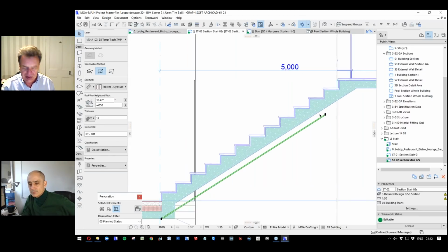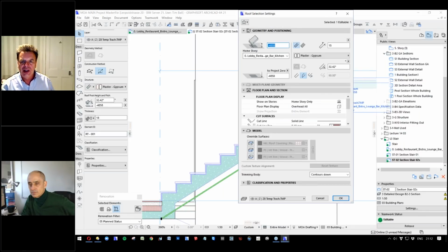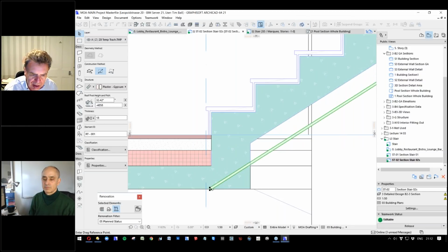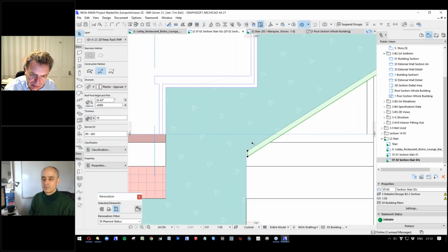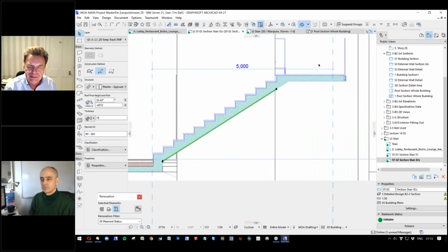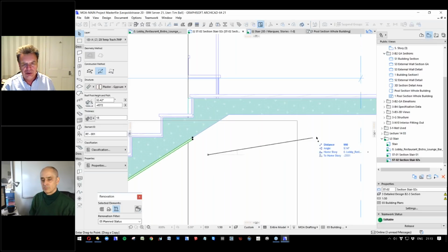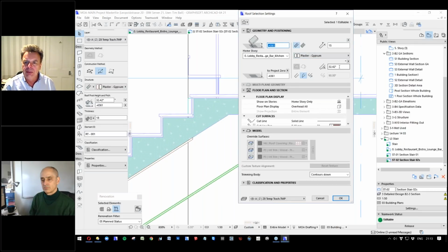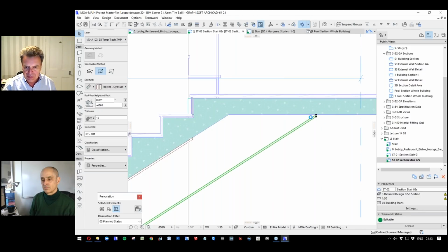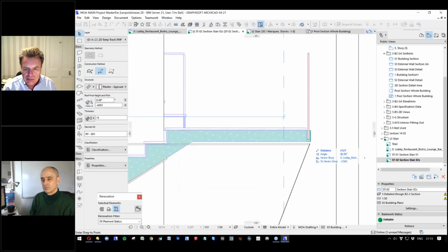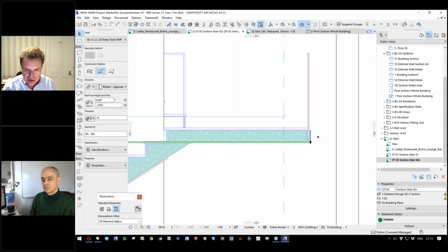So basically, this is actually a roof. You take a bit of roof, you make it plaster, you get the angle right, you get the thickness that you want. I put this temporarily on another layer so I could bring it in, and you take that to there. Getting that connection would be quite nice. We can then do a little trick here. We're going to use another piece of roof here, but we're going to make that 0. We'll come back to that junction in a minute.